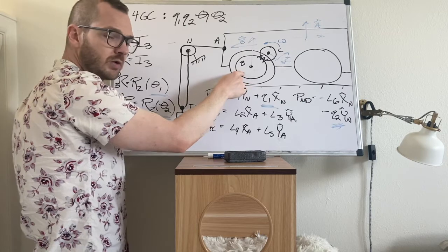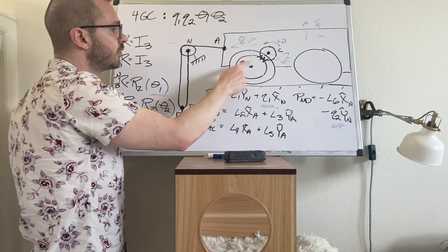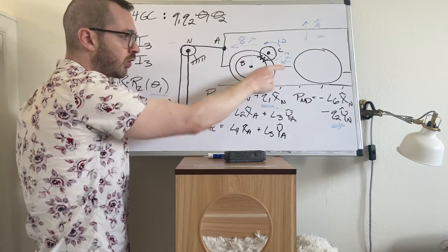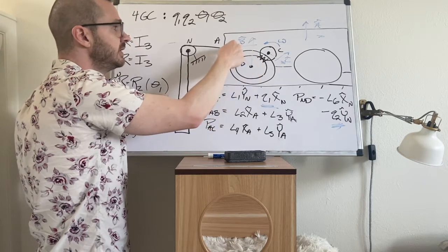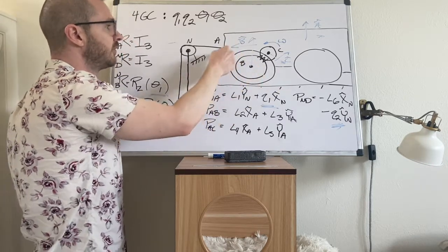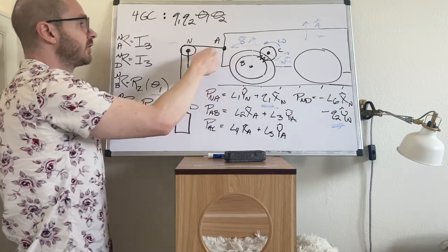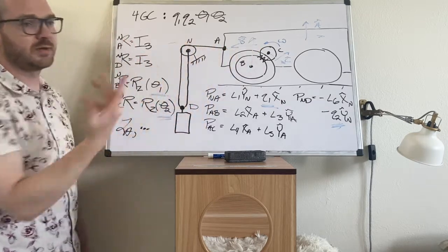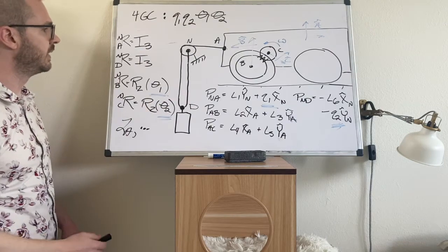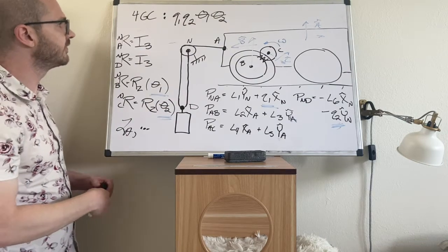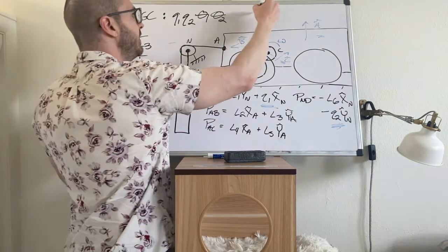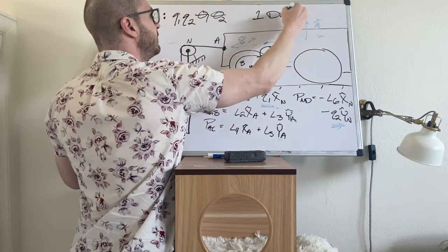So that's going to make the rear wheel spin. And when the rear wheel spins, that's going to make it roll, and it's attached, right, through some kind of suspension or axle or something to the cart. That's going to make the cart translate. And when the cart translates, it's going to pull the rope, and it's going to make the block move up and down. So clearly, this system has 1 degree of freedom.